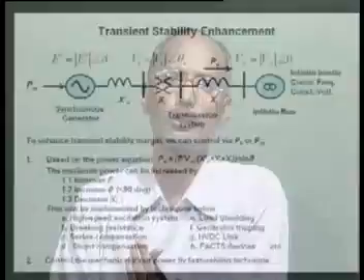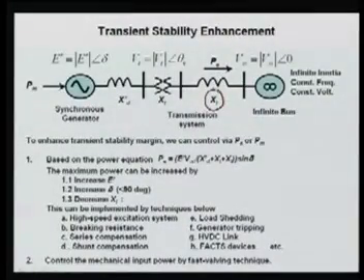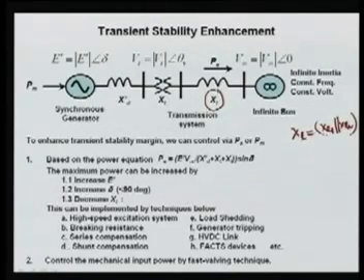Here I have taken only one line so that we can see what is going to be. So it is very easy basically, or you can say we have the 2 lines and the equivalent here is represented by XL. Means if you are taking the same previous example, so this XL is nothing but your XL1 parallel to your XL2. That's simple, we have represented by a single transmission line. This is your synchronous generator, that is PM is your mechanical power feeding to this generator. This is XD prime, the internal reactance of this generator.